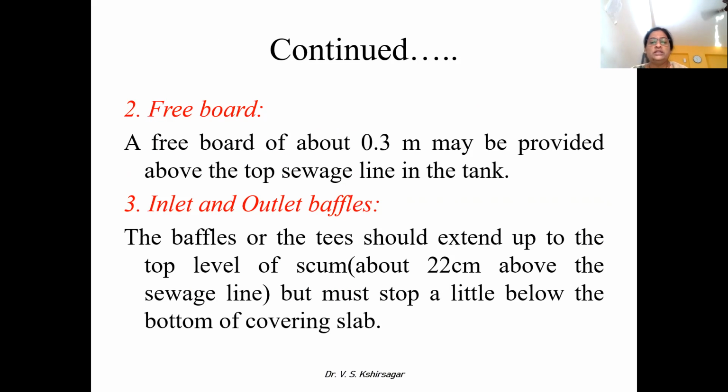So the baffles or the T's should extend up to the top level of scum, about 22 centimeter above the sewage line. Above that 22 centimeter it needs to be constructed, but must stop a little below the bottom of the covering slab. So you are requested to note this down, please.